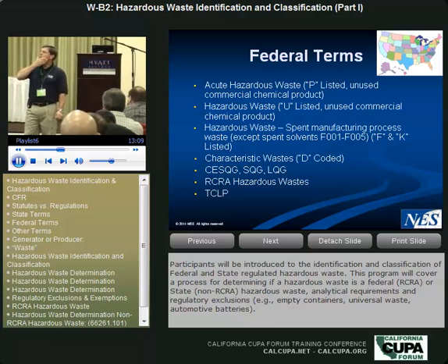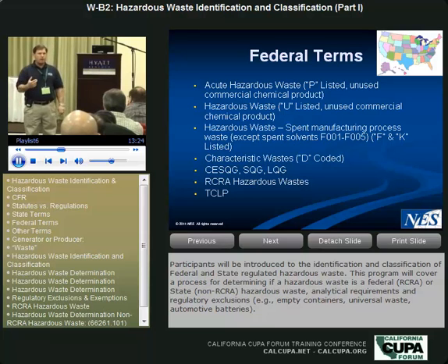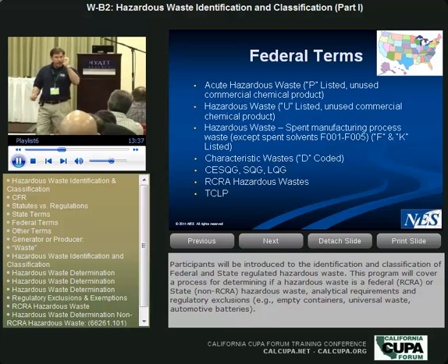So EPA decided that if you had a material contained in a drum, vessel, or a container, and you were going to dispose of it, it's a hazardous waste unless you triple rinse it. And our triple rinse rule that we hear so much about was actually born from those acutely hazardous wastes federally that were listed by US EPA. If they were contained in a container, and I'm going to discard the container, that container is a hazardous waste unless it's triple rinsed.